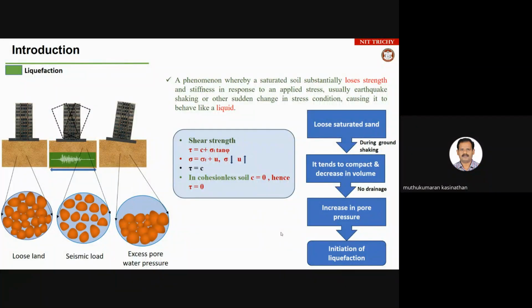Just have a look at this particular slide. What is really happening when you have an earthquake? Look at the left side of your screen. This is the typical scenario during an earthquake. Suppose you have a structure built over a loose sandy soil deposit, and your soil is under saturated condition. When an earthquake comes, it will introduce vibration on the ground.